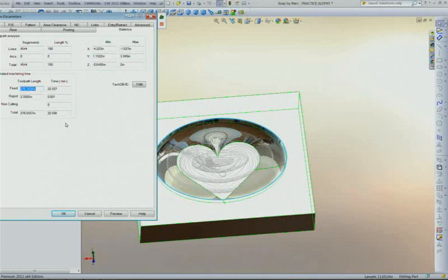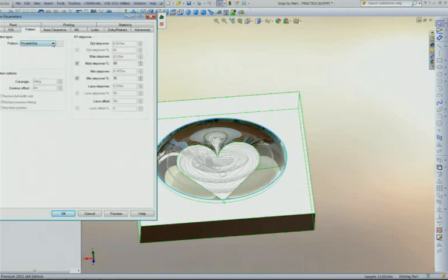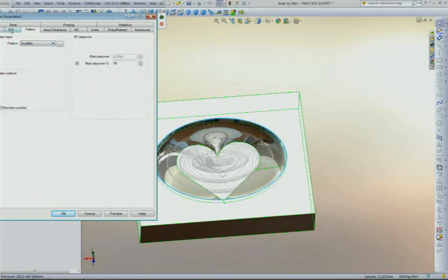You can see this might take a little while to machine this cavity, and with a multiple cavity mold, it would take even longer. So ideally, we'd like to reduce this roughing time. In order to do that, we've added a new feature called Volume Mill. So I'll select the new Volume Mill selection.